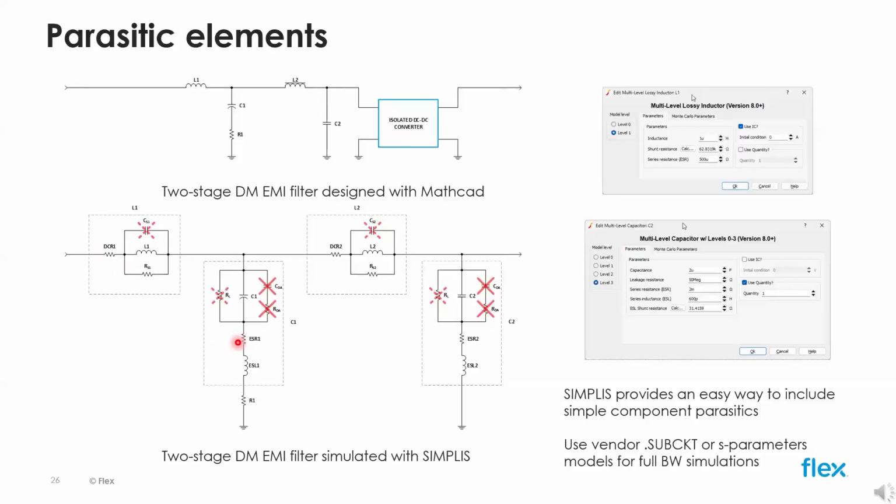The capacitor model includes ESL with its own leakage resistance to approximate the component Q, but in most cases the series RLC circuit illustrated in the schematic is sufficient. The inductor model includes a shunt resistance but no parasitic capacitance to approximate the self-resonant frequency behavior of the component. This can be added manually and we will see how to determine the proper value.